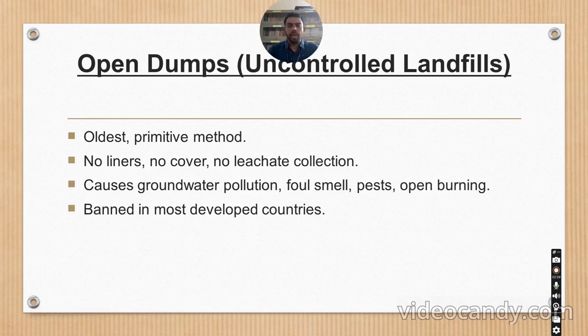Here no controlling measures are adopted. No liners are provided, no covering is provided in these open dumps, and no leachate collection. This is very dangerous to our environment. Such cases produce a lot of problems like soil, air and water pollution.